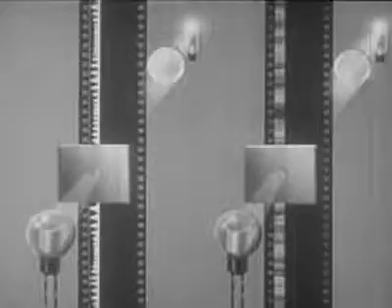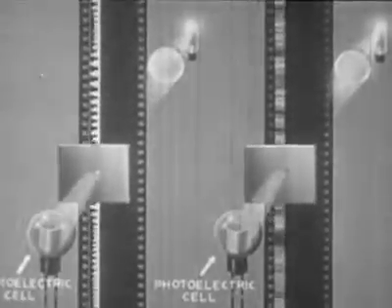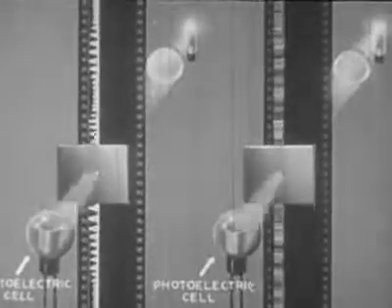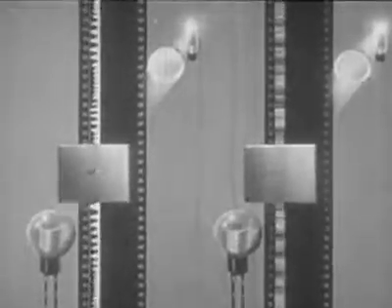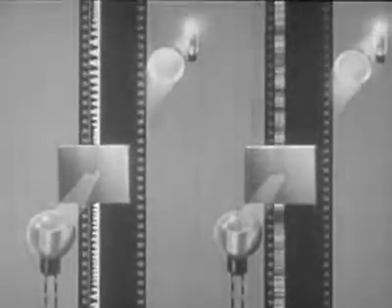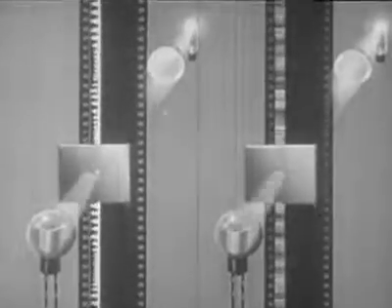There are in common use today electrical devices which will quantitatively measure what the eye can only approximate. The photoelectric cell is one such device and is universally used in the reproduction of photographic sound records. The reproducer system to which you are now listening contains such a photoelectric cell. This varying beam of light falling on the photoelectric cell produces variations in the electric current, which are directly proportional to the variations in the light beam.